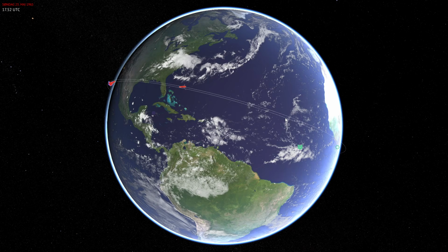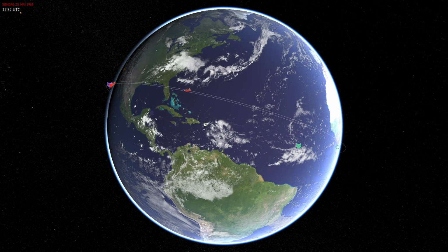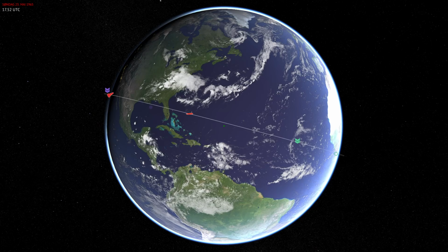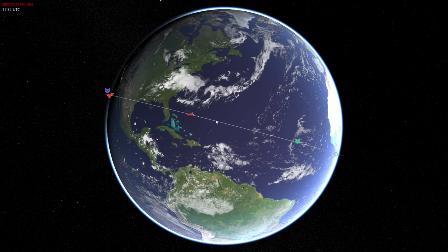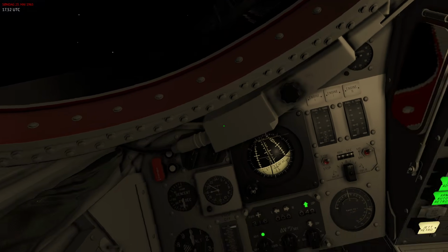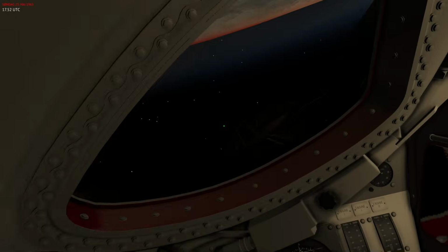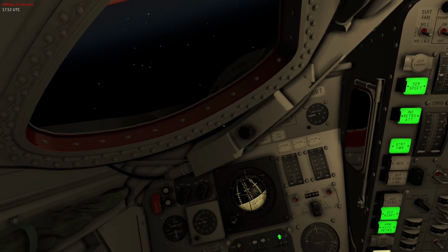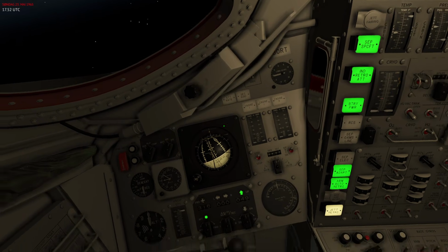And if we would dive down and stayed with the lift vector pointing down, we could land way earlier. But obviously we would also most likely hit and exceed that 12 G limit. So heads down, lift vector up.